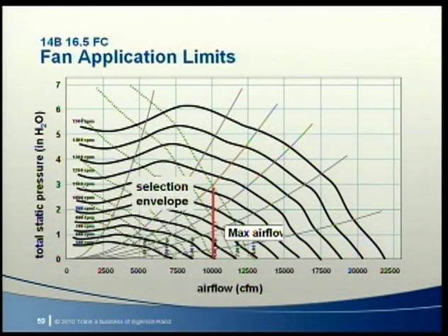Now, we can simply plot the design airflow and total static pressure on the fan curve to find the required fan speed, right? Yes, provided we also comply with some fan selection rules. First, don't exceed the maximum airflow. Even though the fan could produce it, too much airflow and velocity can be noisy or damage equipment.